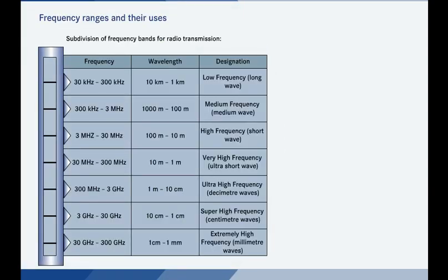The frequency ranges of radio waves are divided into units of 10, from long waves, whose length is measured in kilometers, to millimeter-length waves. Various frequency bands in the frequency ranges are reserved for the different potential applications of radio transmission, from radio broadcasts to UMTS mobile communications. The use of these bands is regulated by law on a national and international basis through a frequency allocation plan. Move the controller to see the European frequency distribution with relevant examples.